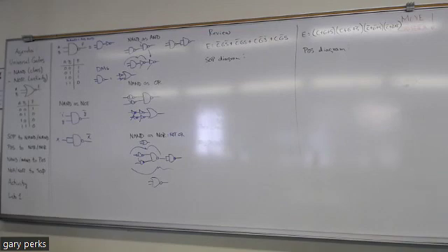And like I explained on the first day of class, the way you can think of that FPGA is sort of like a silicon breadboard, if you will, right? There's logic blocks in there that you can think of as components, and the interconnects between the logic blocks are programmable. So when you write Verilog code, you're selecting what parts of that silicon circuitry you want, along with how it's all connected, instead of doing it manually like you do in an analog lab, like in your Circuits 1, Circuits 2, or Circuits 3 lab.